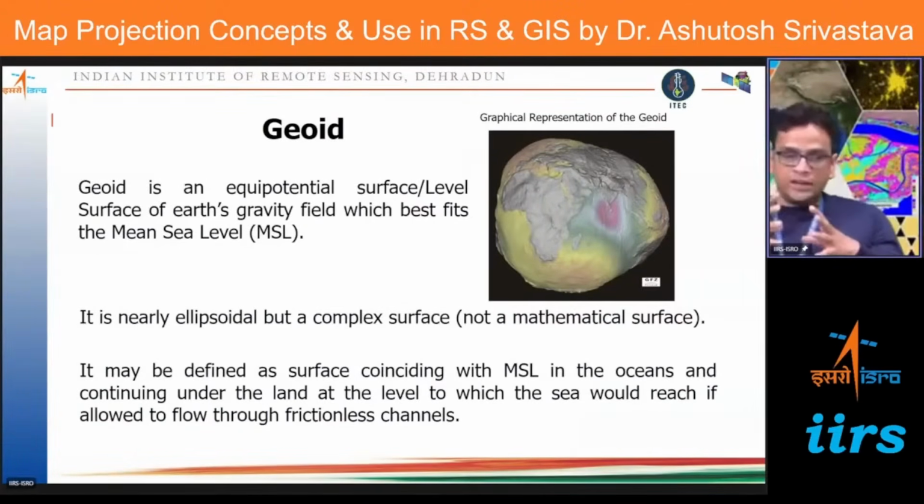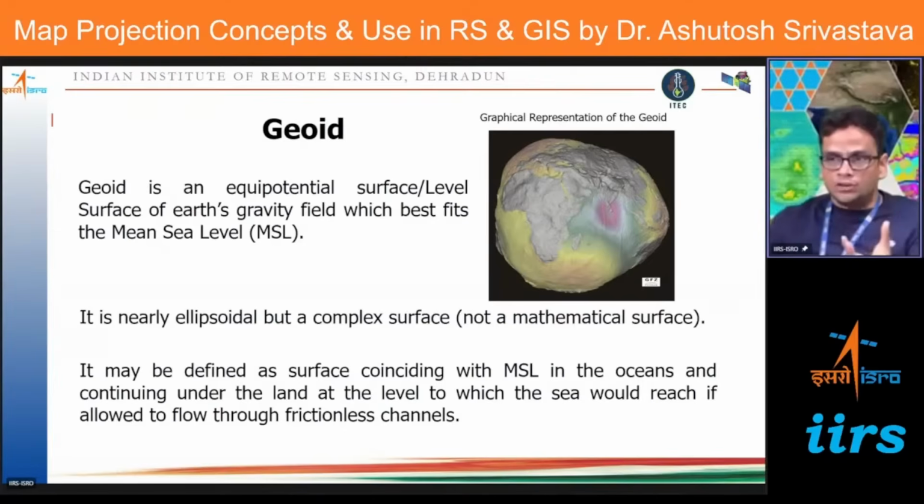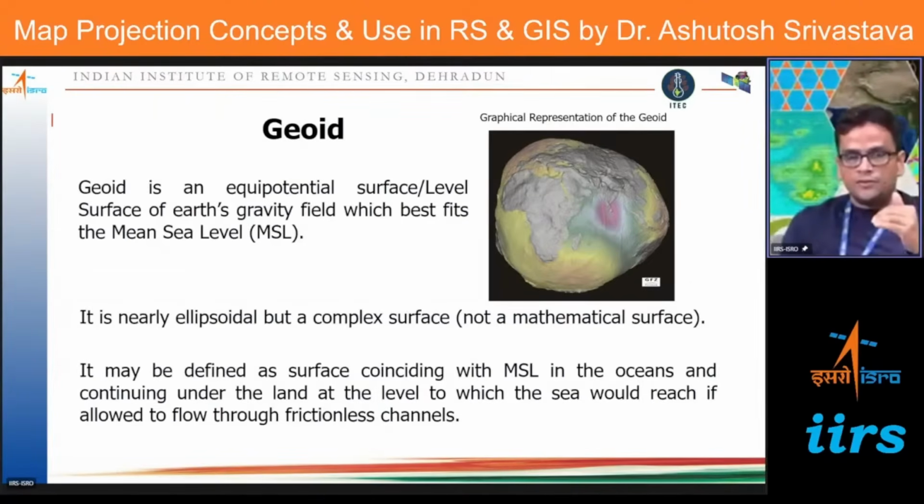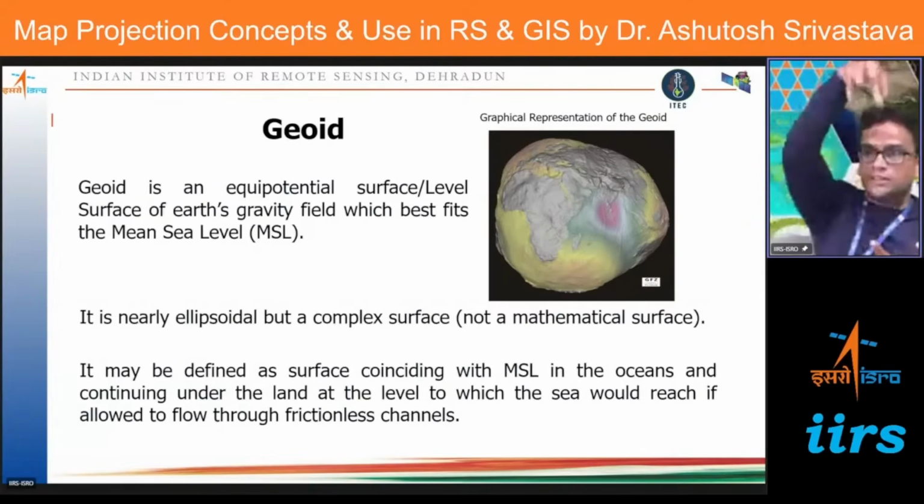So once you generate your ellipsoid, the next thing is to make it more real, so that it can closely represent our Earth. Since it is only an ellipsoid, we have to fix where the north, the Earth's rotation axis, should be. This is our Earth rotation axis. Where should the equator be? Where should our reference point be? You have to fix the X, Y, Z triad in that ellipsoid.